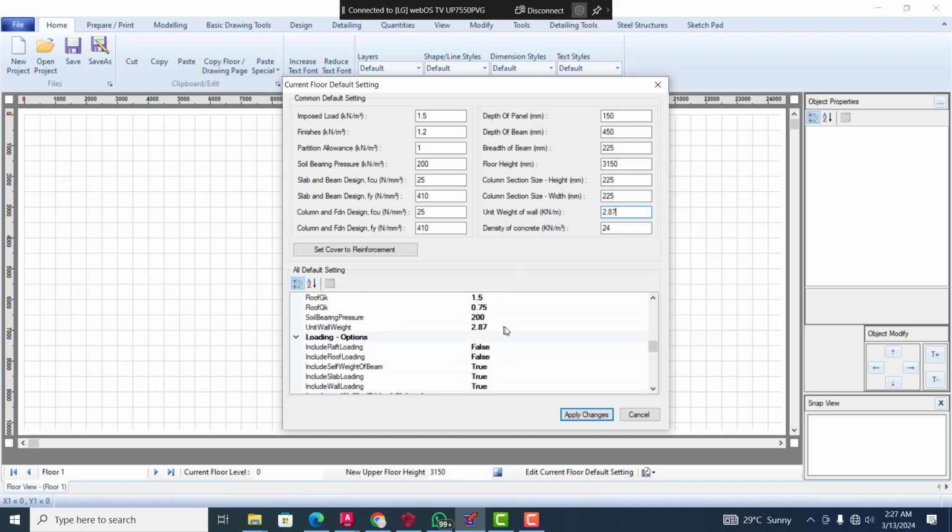If you look at this down here, you can see there is some other information that I can change or I can add. So if you look at this, geometry is telling you the breadth of the beam and the height of the column. When you look at the cross section of that column, it says 230 by 230, and then the height of the column will take the height of the building, which is 150. That's coming from the architectural drawing. You can go down and change some other few information.